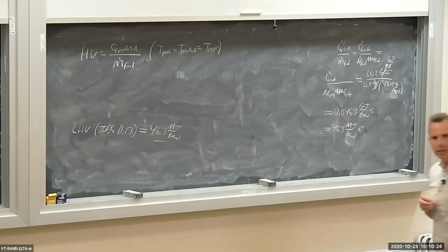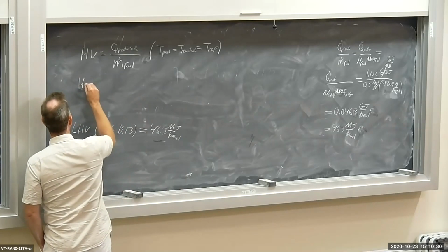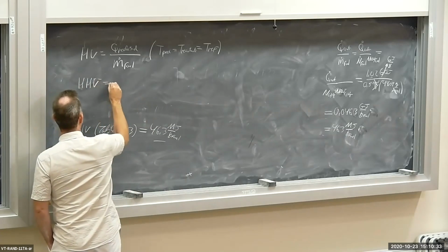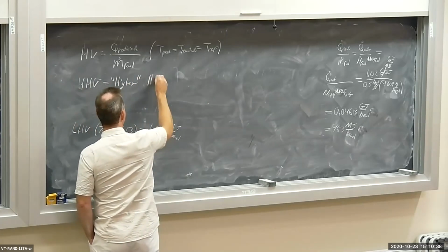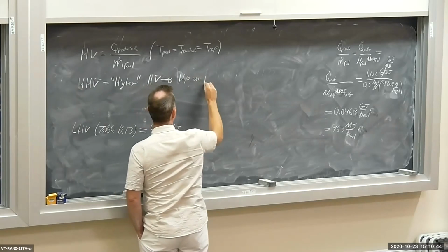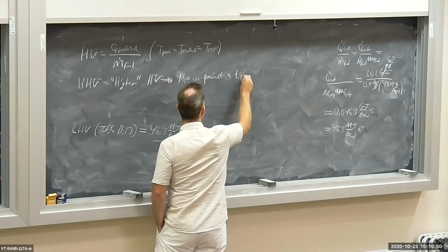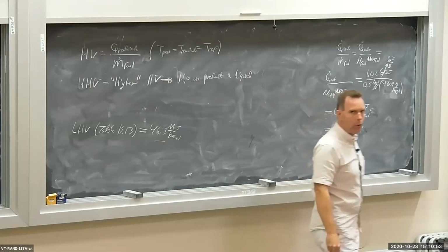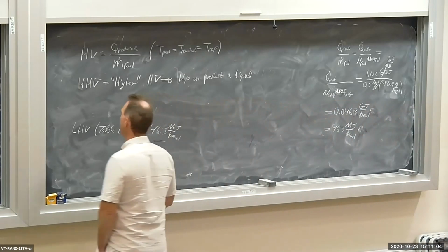So again, let me make sure you understand the difference between lower versus upper heating value. The higher heating value implies H2O in products is liquid. So the H2O formed by burning the propane or any hydrocarbon fuel ends up as a liquid in the product, and we can extract out as much heat as we can from the products.